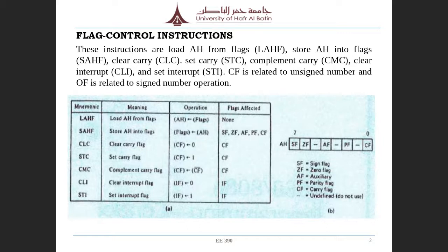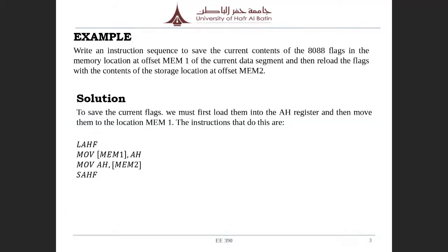But some instructions are specific to a particular flag, like CLC, clear carry flag. It is specific for the carry flag only. The carry flag will be cleared, that means reset. Whatever it is, it will be reset. If it is set, it will be reset. If it is already reset, it is unchanged. So these are the things we already discussed.